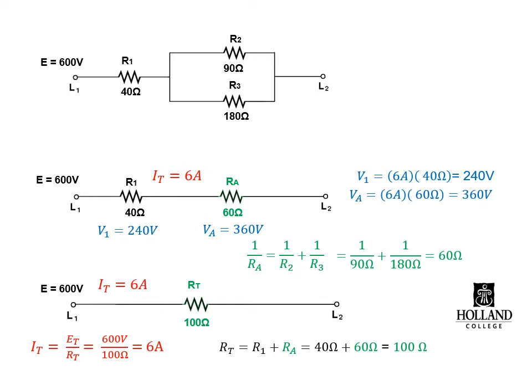At this time, we would do a check and say, it's a series circuit, and what do I know about series circuits? Well, current's common, resistances add, and voltages add. We would use Kirchhoff's voltage law to see that those two resistances add up to the source voltage. And they do.